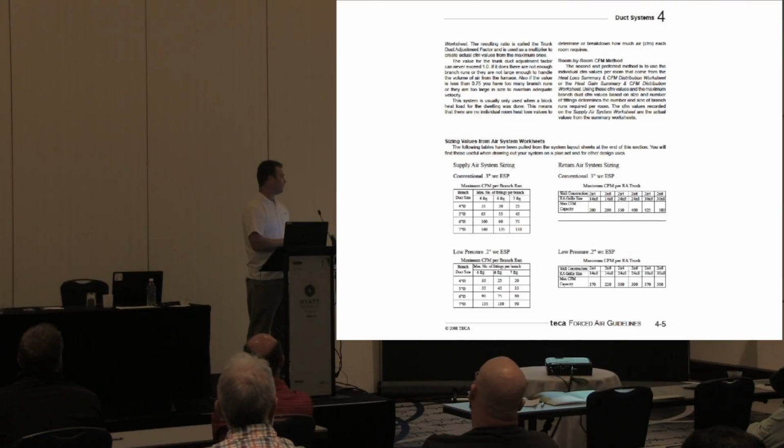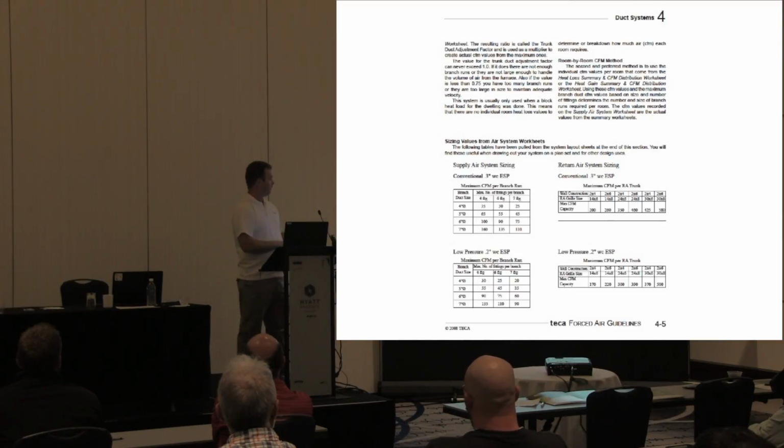In the 10 years I've been on my own, since I started my own business, I've never run a 7-inch run, just because they're too expensive. We just put more 5s in, or more 6s, or a 4, or whatever we need to do. The grill sizes will always be the same, so the homeowner isn't going to see anything different once you board everything, but it will cover it.